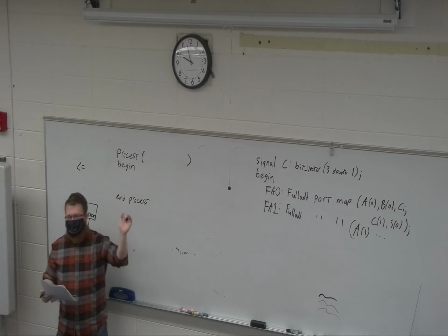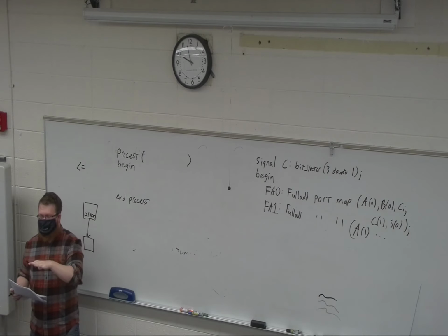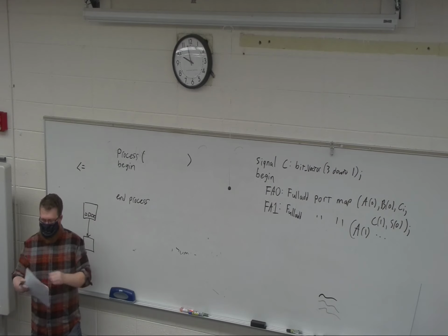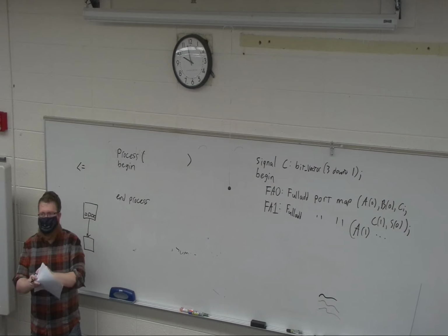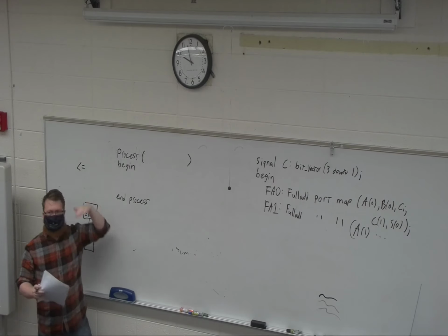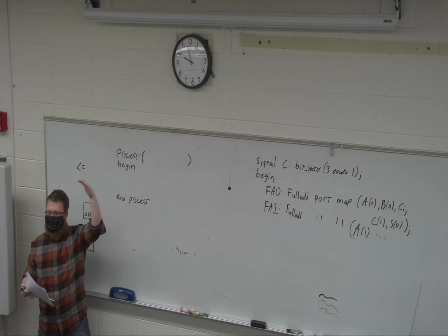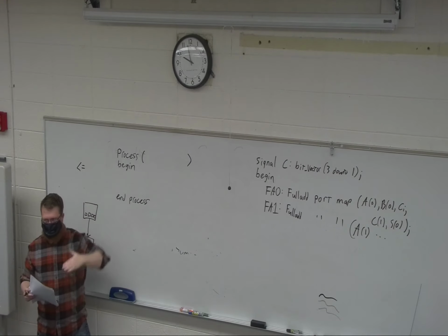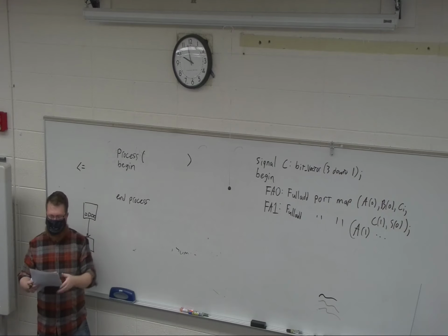If you were to say put A and B in there and forget D, then D could change all over the place and it would never react until A or B did. And once it's started, so say A changes, and then halfway through the reaction, B changes, it's not going to restart the process. It's got to finish the process before reactivating.